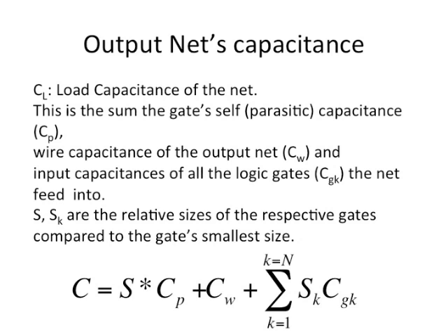There are source drain junctions, some internal source drain junction capacitance inside the logic gate, the Miller capacitance, etc. And then there is the wiring, because the net consists of a wire which connects the output of this gate to the inputs of other logic gates that it feeds into. So the wire has a capacitance to the layers below it, layers above it, etc.